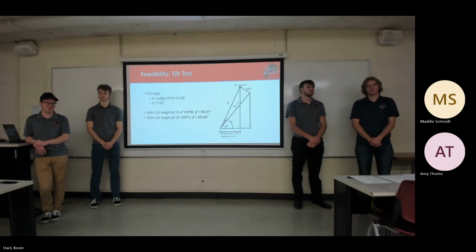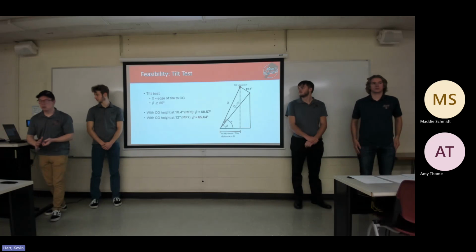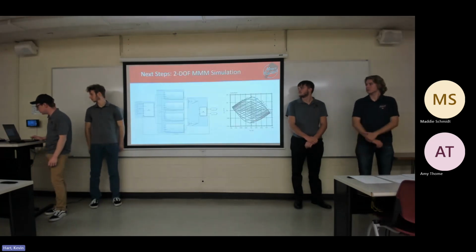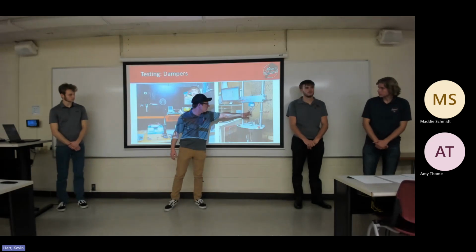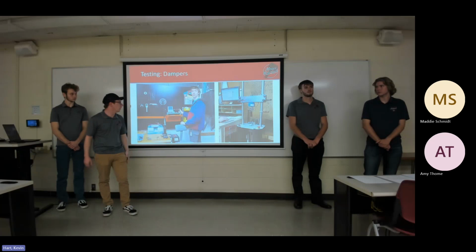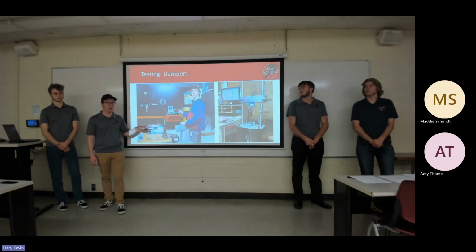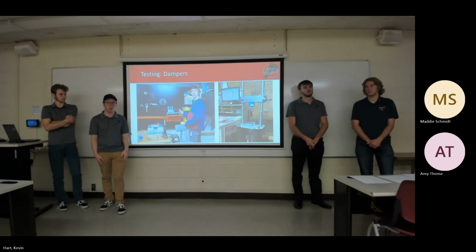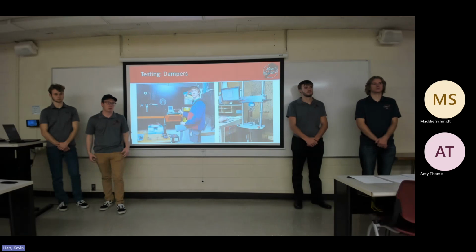For the dampers, you said the damping was set at something? Was there a certain number that they used? And how did you get that number? The shocks have clickers in them. It's hard to tell in this picture. There are these knobs here that change your compression setting. So we ran tests at various settings and then interpolated the data to get what the relationship between force and velocity is for each of those settings. Oh, so you did do different settings? Yep. All right.